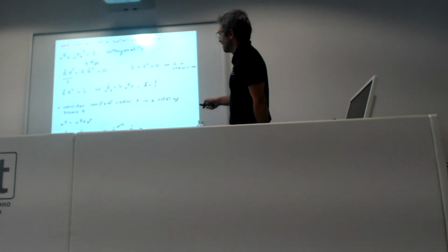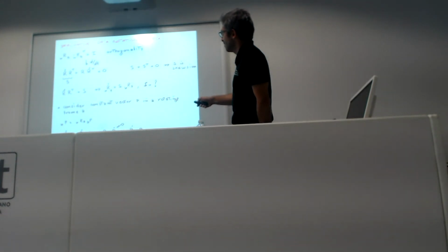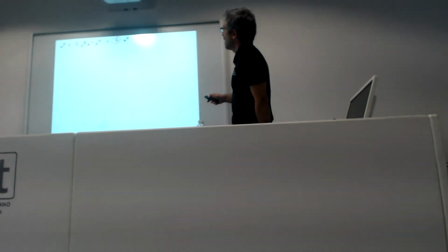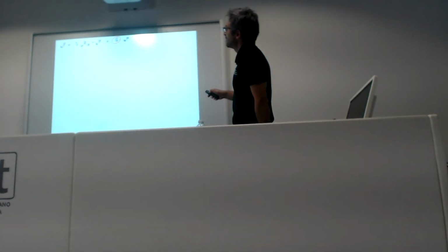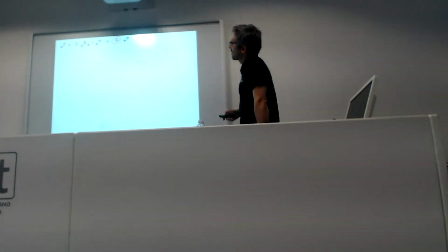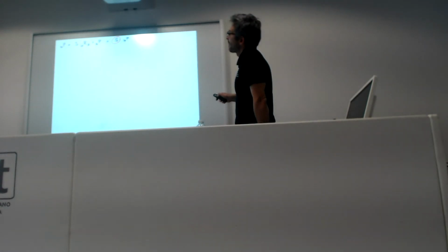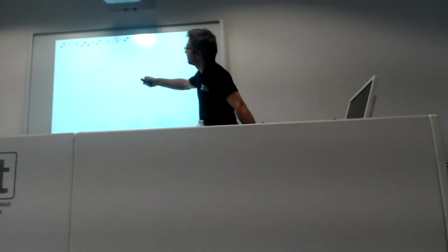But if we replace what we found here, r dot, we get p dot w equal to S r bw times pb. And these two are nothing else than pw. So we map the position in the base frame back to the world frame, and we have the position in the world frame. Sorry, this is a dot here.